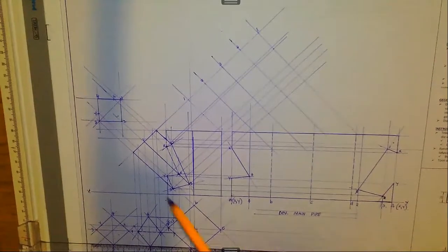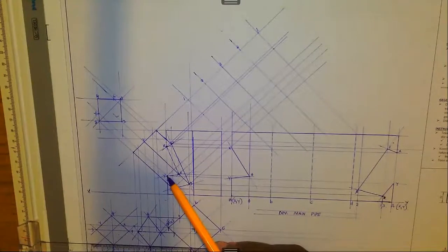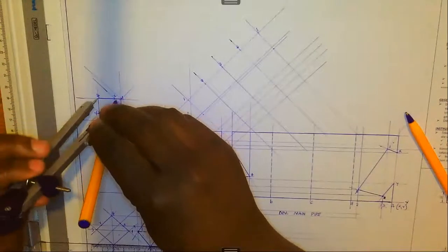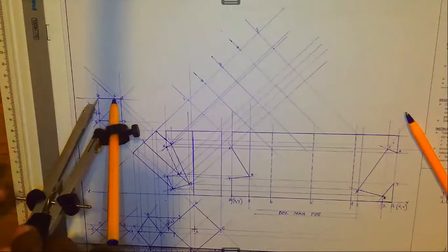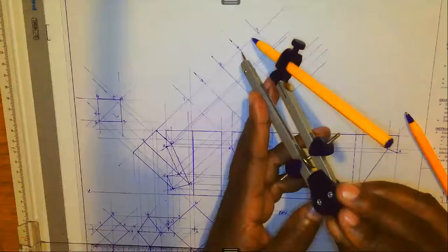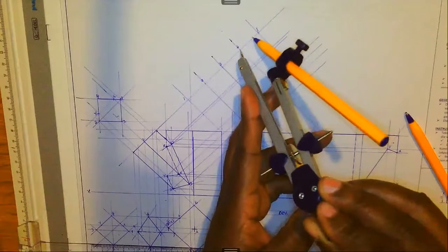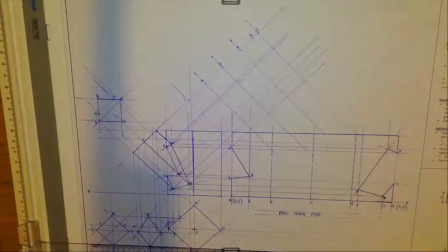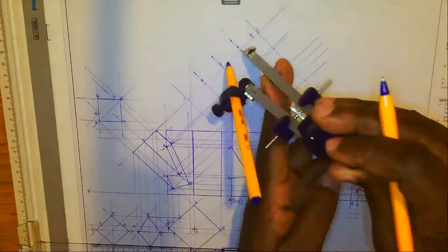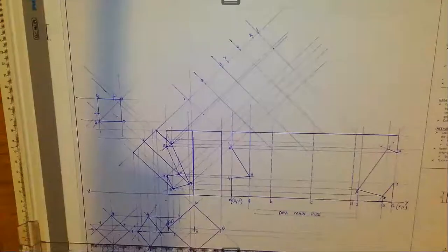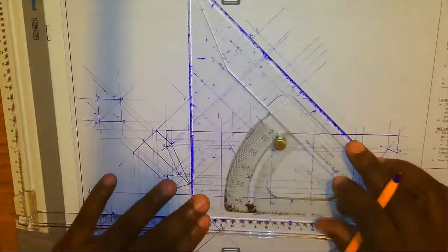Then from there, we also need to establish point X and point Y. This is what you do. You go back to your auxiliary view, take the distance between 4 and 1, like this. Look for point 4, you stand there towards point 1, you mark like that. That's point X. Stand at point 4 and open to point Y, towards point number 3, you mark like that. This is point 1. You project these lines as well, faintly,